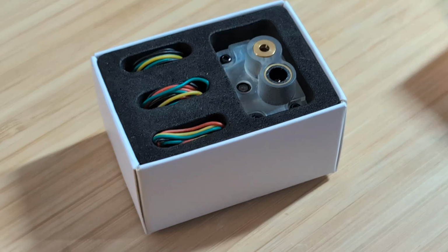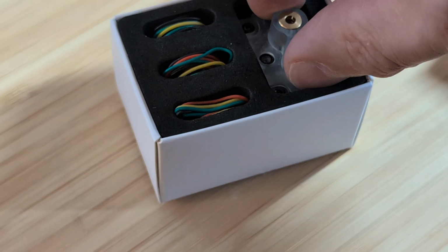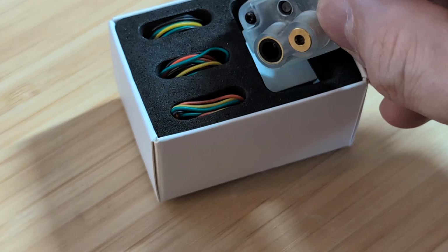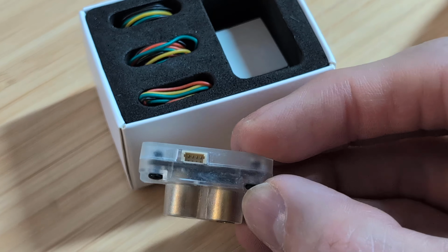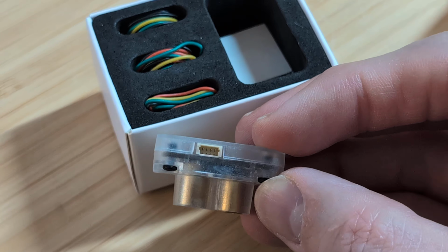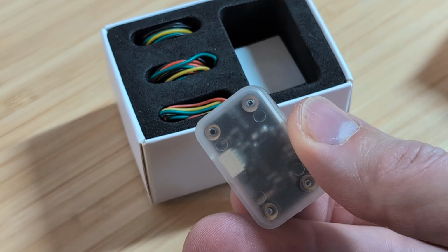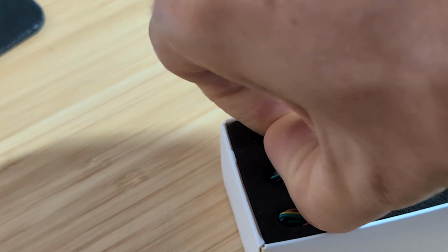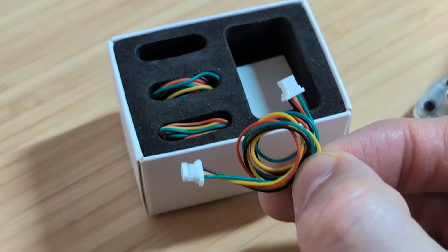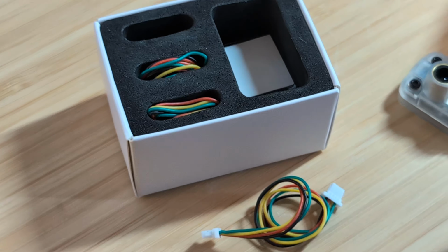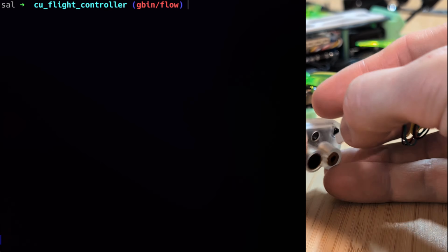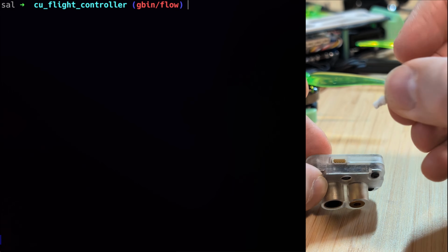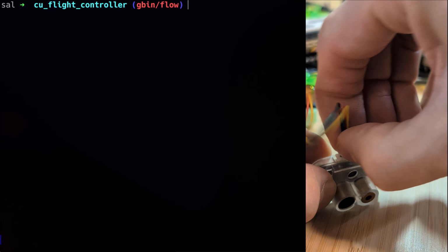For this sensor, we'll use a dual sensor that does both a 1-point LiDAR, basically measuring distance, and also optical flow. Inside this device, there is something close to a video compressor, and with blocks and differences between blocks within the video, it can compute the flow of the image. You then get an X and Y vector in the direction the image is flowing. So that's quite exciting.